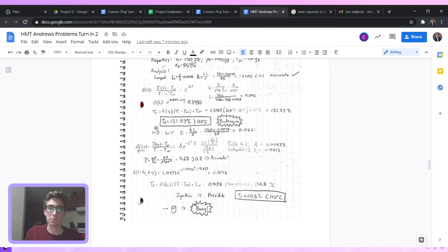Doing the same analysis with 1D spatial analysis, the critical length is now changed to only the radius of the sphere. Next, the Biot number is found, and this is used to find our constants, our A and gamma constants, which are then used for the transient analysis.